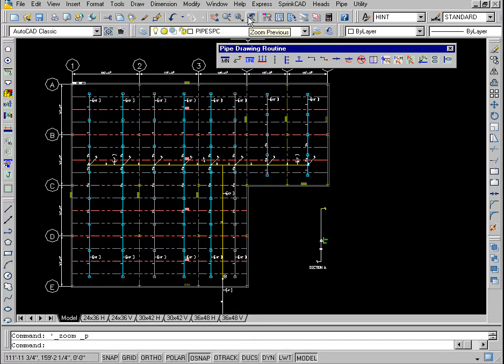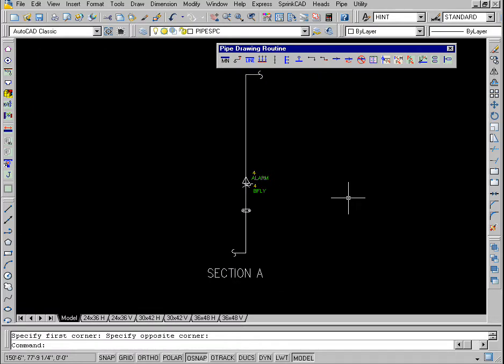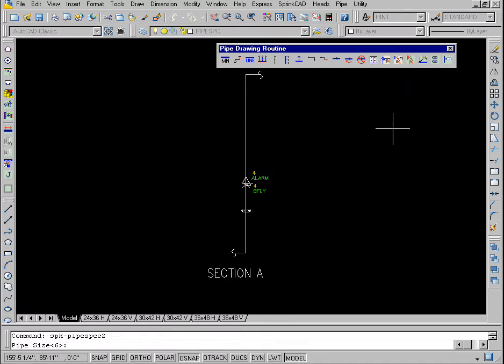Now you can size the riser section. Use Multiple Pipe Size to size the pipes. In this system, the pipe above the alarm valve and the pipe above the stub are 4-inch Schedule 10. The vertical piece below the stub up is 6-inch ductile iron, which is the same as the underground in the plan view. Do not size the short stub pieces at the top and the bottom.